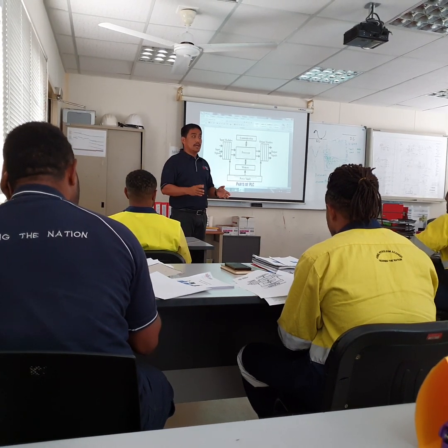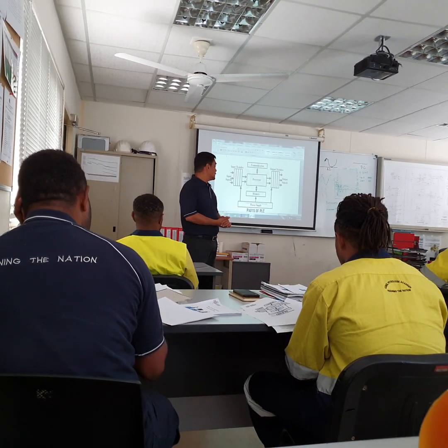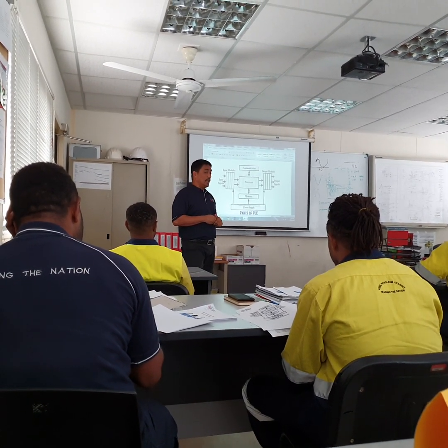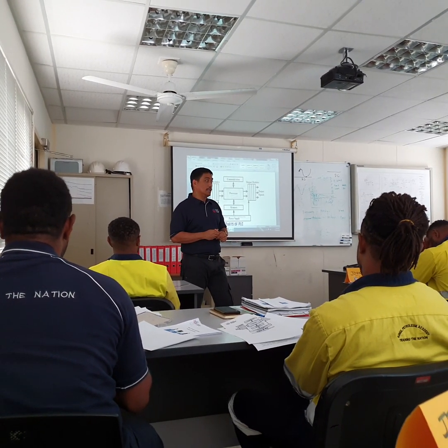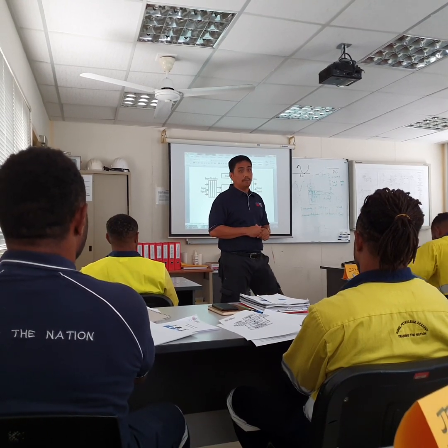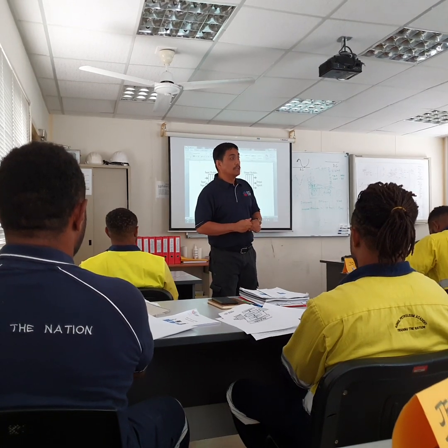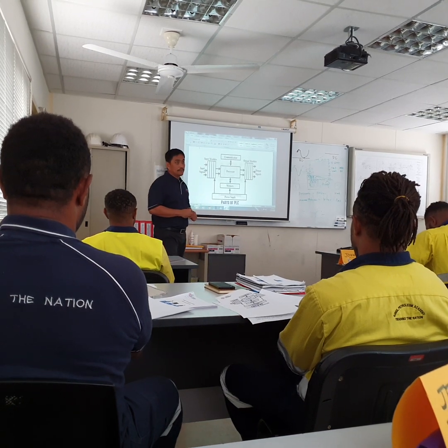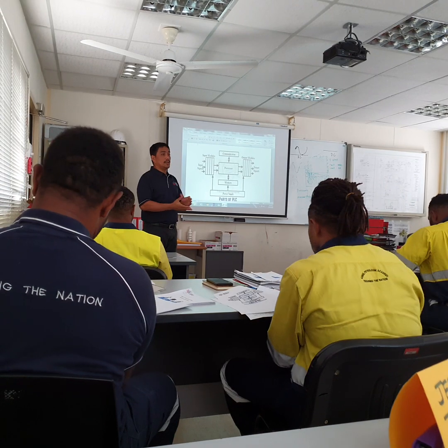Digital input means 1, 0, 1, 0, on, off, like a switch. Analog module is a certain signal. Analog module can be the 4 to 20 milliamp, can be a voltage 0 to 5 volts DC, or can be a temperature giving a certain value like an analog. Output module, we have digital output also and analog output.